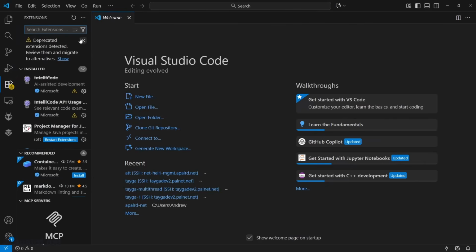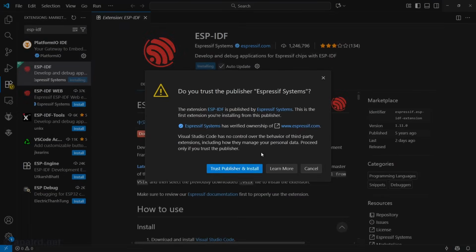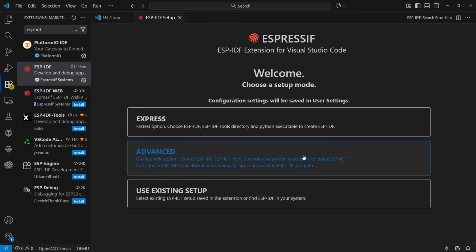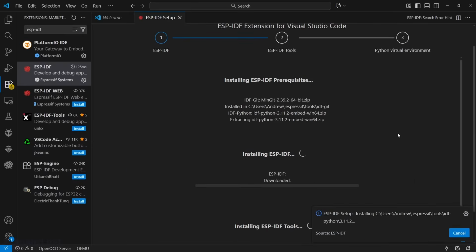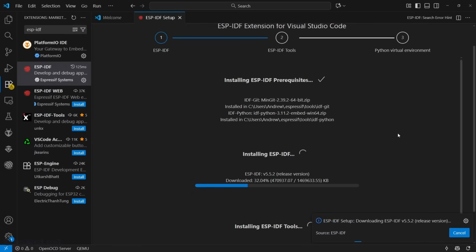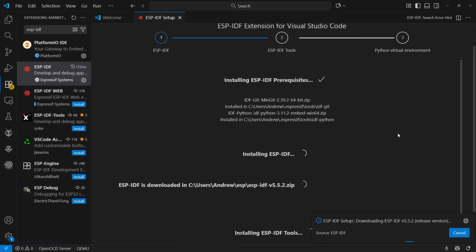I chose the hard mode approach. I am an embedded programmer, or I guess I was before I became a YouTuber, and so I am perfectly happy writing bare C code and compiling it. So I used Espressif's ESP-IDF. This is the very excellent dev chain from the chip manufacturer Espressif. They actually have a Visual Studio Code plugin, so I didn't have to install any software manually. I can just load the plugin in VS Code, and then it downloads all the toolchains and all the libraries I need, and it's ready to go. So that's what I did for this project.